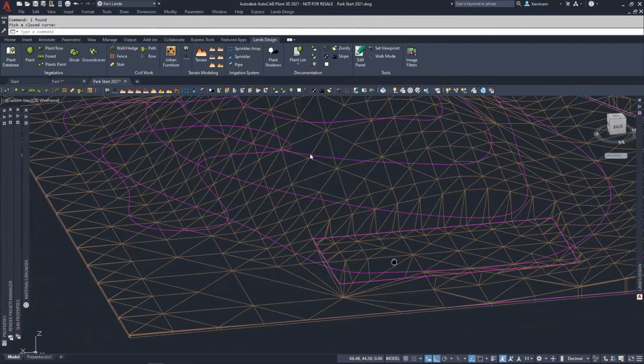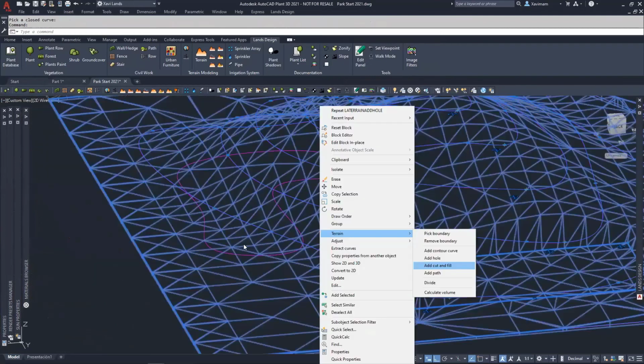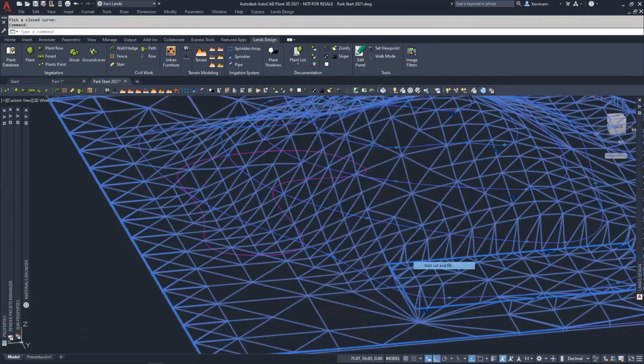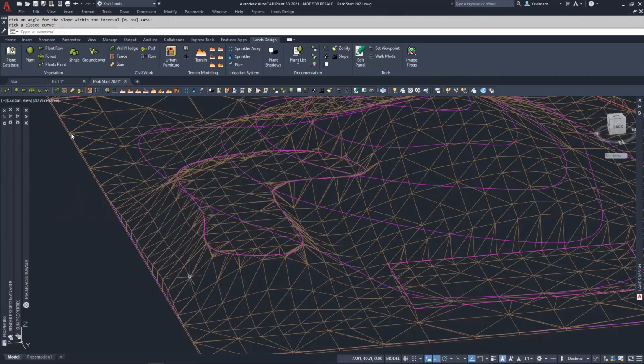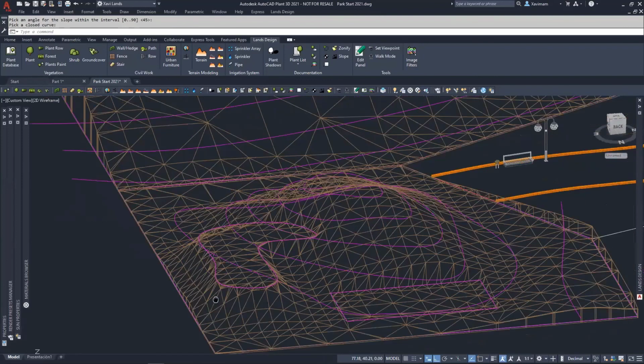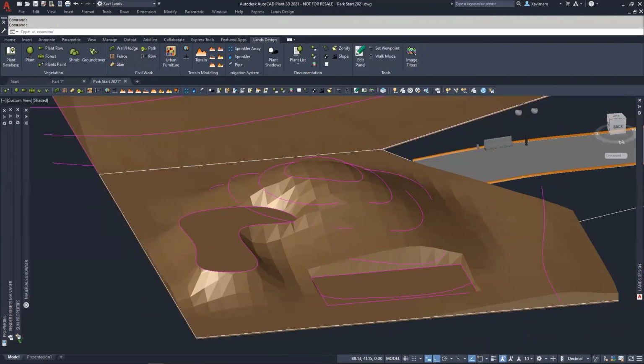And as we saw, I created the spline. Some part of the spline is, let's say, up in the air, but the other one is fitted inside the hill. Then if I say cut and fill with this contour, first of all, I have the possibility to add the angle. Always follow the command prompt area, because the program is going to drive you through the options. And I'm going to place 45 degrees for the slope areas. And then it is asking me for a close surface. And now I can go back to shade mode. And we can see here that we have the details placed in my terrain.